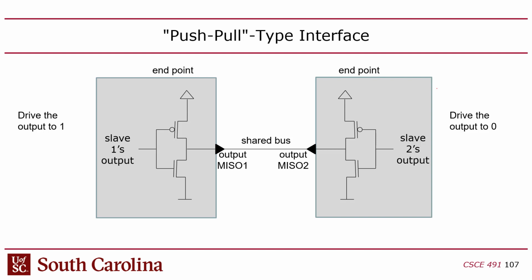So one of these will be low impedance, connecting the output through it, and the other one will always be high impedance, and they'll switch, right? So they're complementary. Makes sense? One thing I forgot to mention that's important is the input to the driver: internally on the chip, you have an output bit you want to send out to the bus.